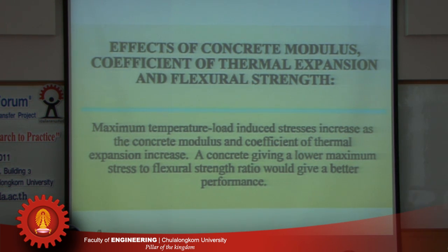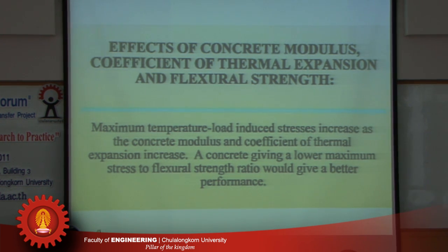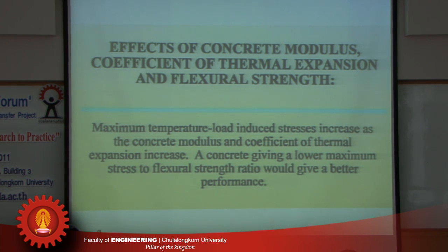So if you want to evaluate between different concrete mixtures, we need to do the proper analysis. The one that gives us this lower stress to strength ratio would theoretically give us a better performance. You cannot judge it just based on one parameter. Okay, we cannot say that, well, this concrete, because it had a higher coefficient of thermal expansion, it may be worse. Well, it could be worse, but we have to look at the whole picture, okay, and judge it based on stress to strength ratio.